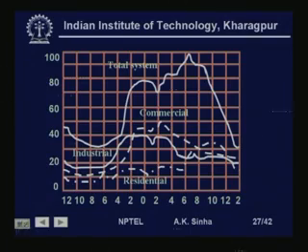So, when you switch on a supply, immediately this power comes by getting extracted from this kinetic energy of the rotating mass, and because of this extraction the speed of rotation will slow down, that is, the rotating mass will experience some retardation. This is what we see in terms of change in frequency or reduction in frequency.